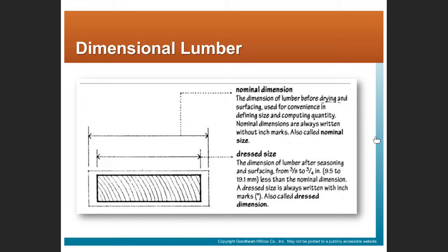We'll see in a minute what the actual size of a 2 by 4 is, right? So the dressed size is the dimension of the lumber after it's been seasoned and finished, right? The dressed size is less than the nominal dimensions. And the other important thing here, it says the dressed size is always written with an inch mark.